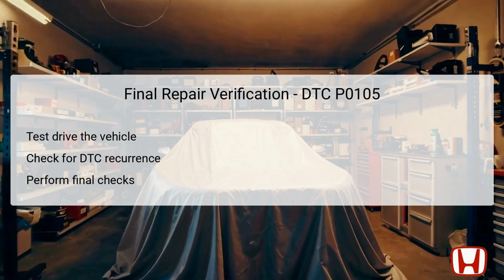After the drive, utilizing the HDS once more to confirm that no new DTCs have been recorded is essential. Final checks should revisit all repaired connections, ensuring they are secure and free from contamination or corrosion. This process validates that the initial issue has been completely resolved, enhancing overall engine performance and reliability.